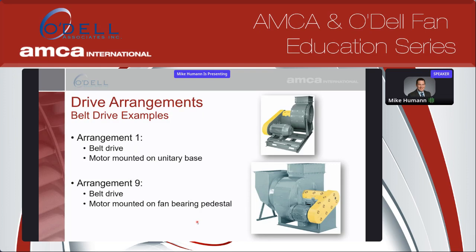With the belt drive, you do have a lot of flexibility for running speeds. You don't have to be at the motor synchronous speed, and you can even be further from it than you could with typically a direct drive fan. Arrangement 1 would be better for really high temperatures. With arrangement 9, you do have that motor tight to the housing. So if you have elevated temperatures, over 400 or 500 degrees, you certainly want to at least account for that, if not change to an arrangement 1 potentially.